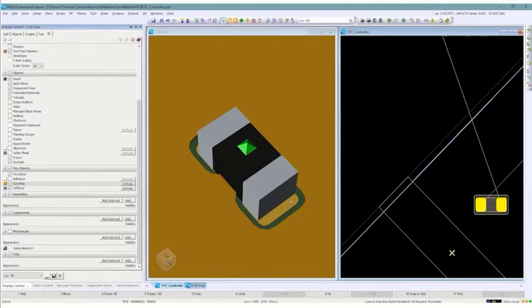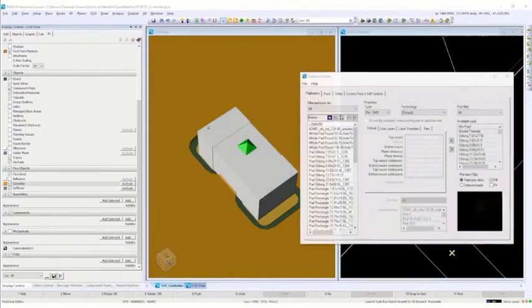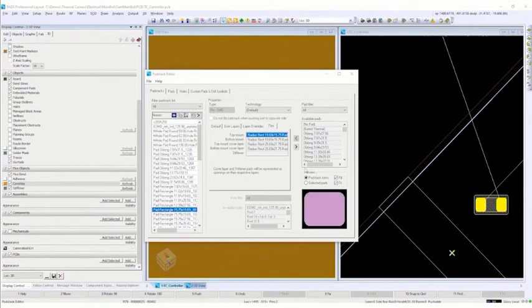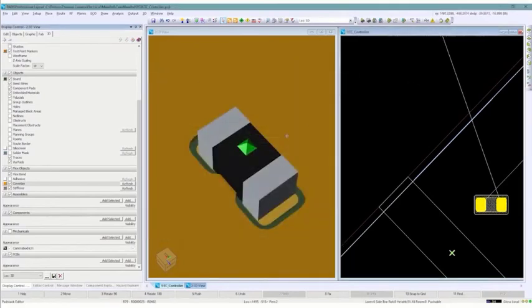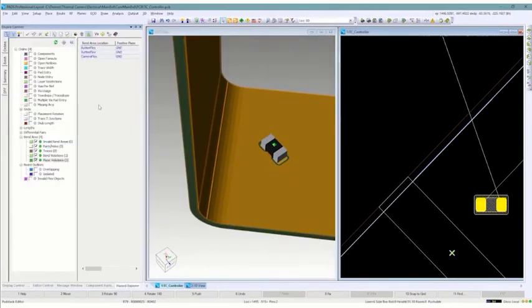You build this into the part. There's special capabilities there. We can take a look at it just real quick. Go to libraries, pad stacks. Here's the pad that's being used for this part. You'll see there's a flex tab here, and I can define special geometry for the cover layer opening and the copper pads themselves. So the tool will automatically take care of the switching from square pads to rounded pads on a flex region for you.